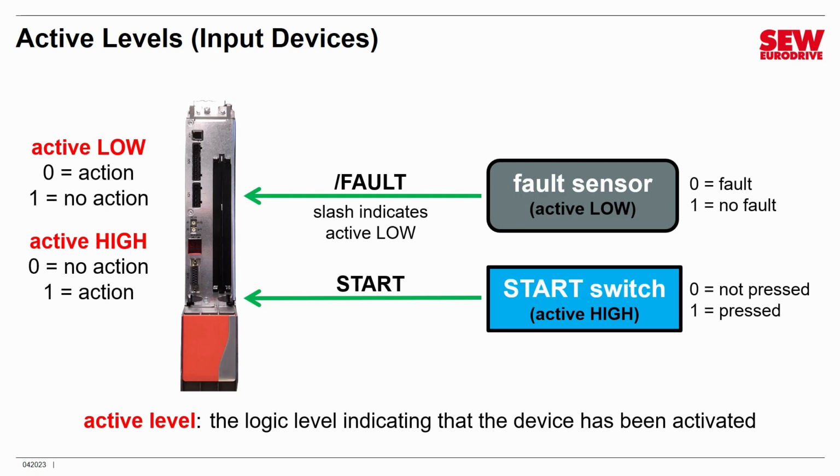Of course, many switches and other control devices don't do critical things. For example, mode switches might not really do anything important, and in that case, it would be your call which you used. Many of those would be active high just because it's a little more intuitive. But do understand that's why active high and active low both exist. Active high devices have signal names without a slash in front of them, so absence of a slash or bar means active high. Nothing too hard about that.